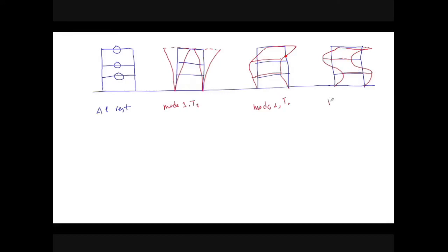So in this mode, you can see that this is now the mode shape for mode 3, having the oscillation time period T3. Okay, and if you compare this with the original deflected shape, you can see that there are two crossing points, these two knots that you can see there, and when there are two crossing points, this will indicate the third mode.